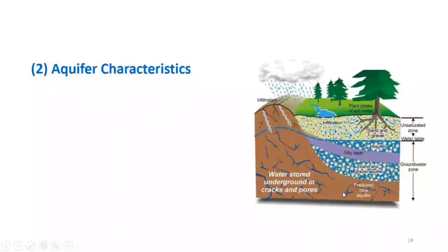What type of bedrock do you have? Is it fresh rock, which is unweathered, or do you have fractured rock? All these things will actually control what type of method you will use, because every method is not applicable to all these situations. So you have to select the representative method for the conditions.